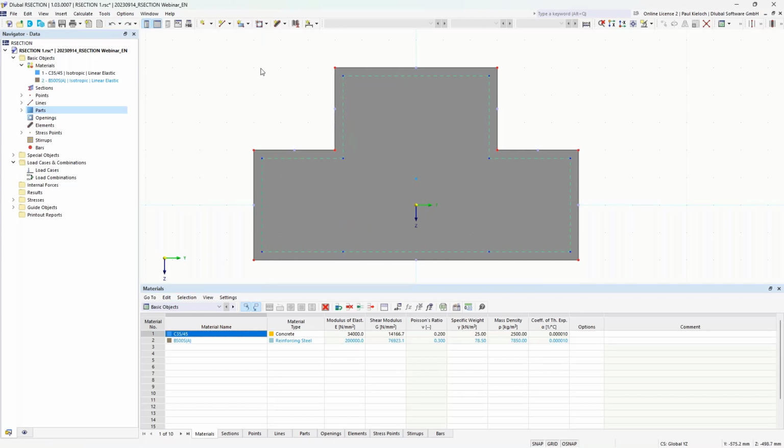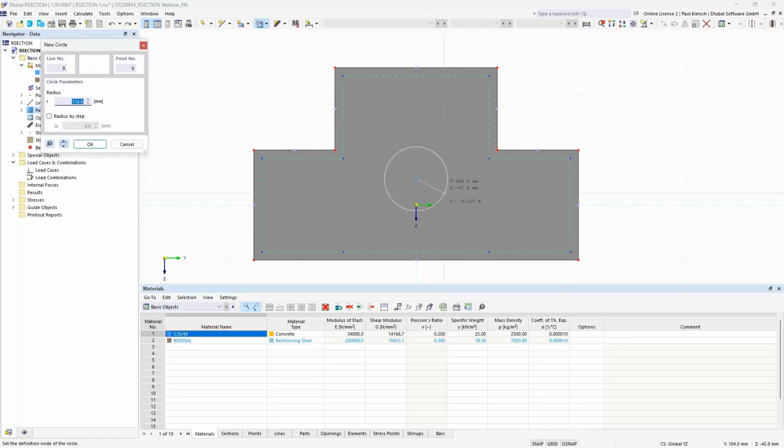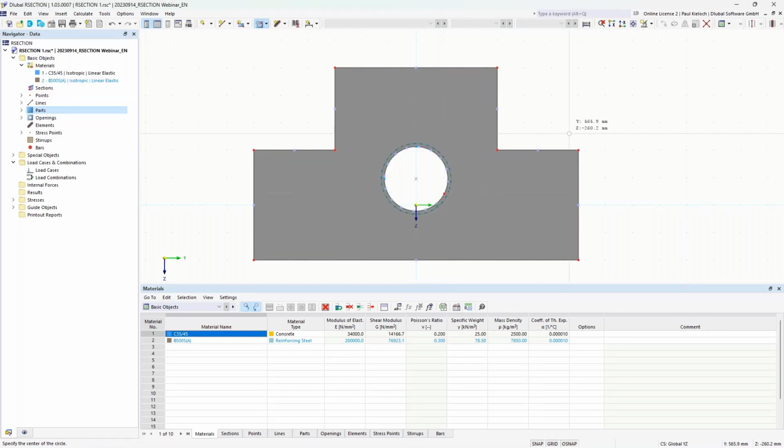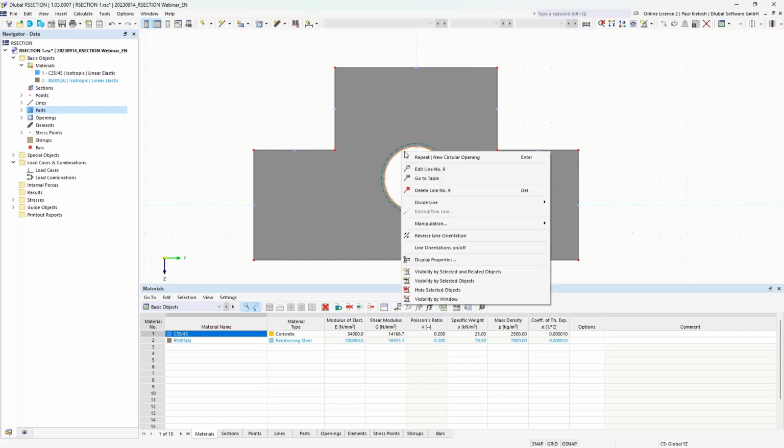If you would, for example, enter round or circular openings in a section, for example, to create a hollow core slab, then you can use this option. If I would apply a circular opening, then the program would delete the concrete covering. That is caused because the program is in the current state not able to generate the concrete covering for arcs or circular parts. So therefore, we can make a short workaround for it.